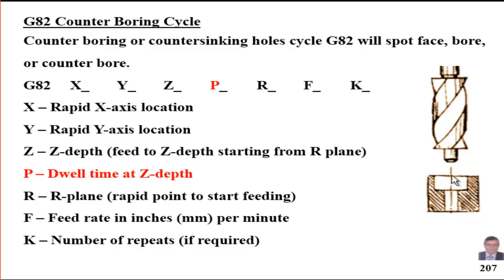So to avoid any bolt or any washer or any projection above the machined surface, we enlarge the hole. So counter bore requires initially a drilled hole, and afterward we use that type of counter bore tool to enlarge the hole.